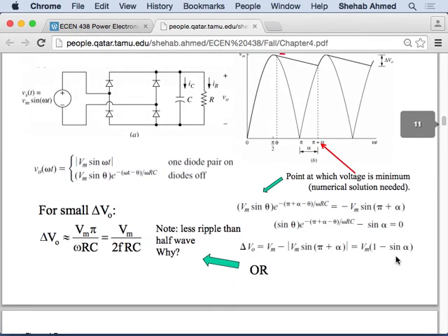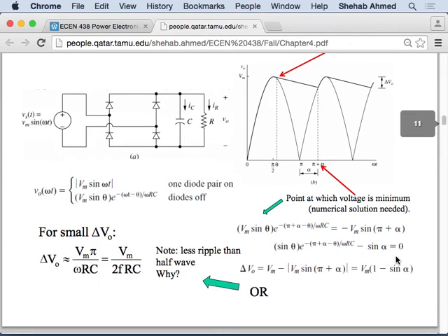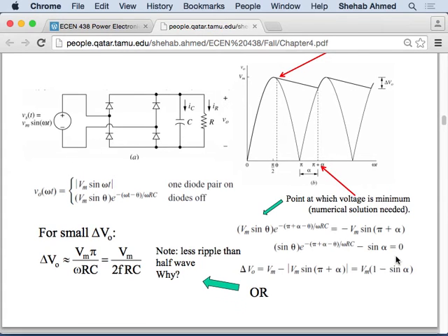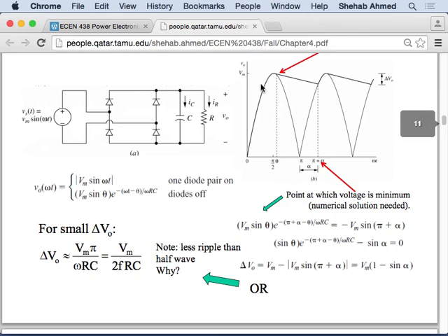So we've covered most of the classical rectifier circuits. Sometimes there are special cases. I want to convert from AC to DC, but I want to double my voltage. Like here, my input voltage is this AC waveform, and my output voltage's peak value is going to be equal to my input. But what if I want my output voltage to be double my input, and I don't want to use a transformer? I can use a transformer after here, a 1 to 2 step-up transformer, and get double this. I can do that.